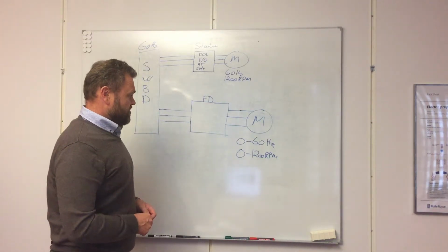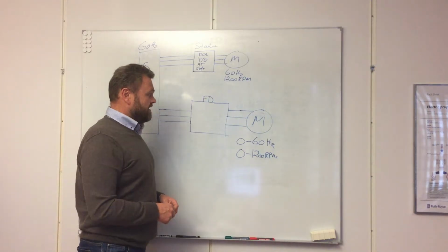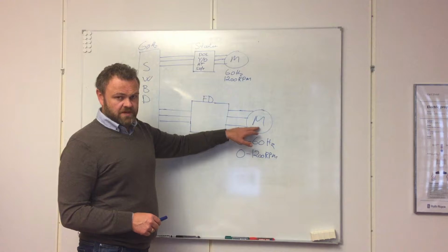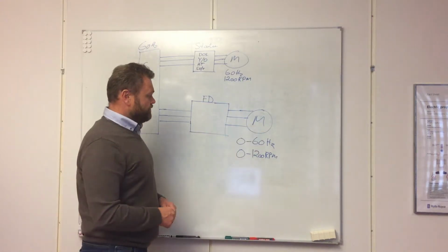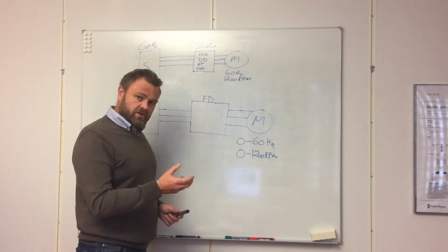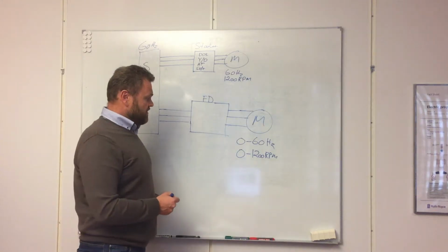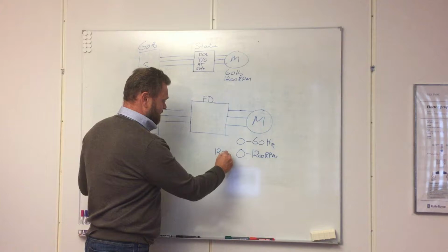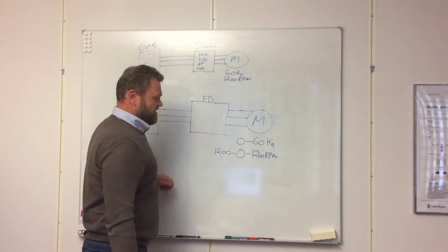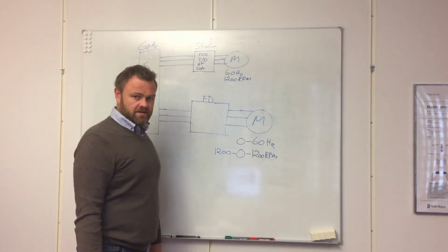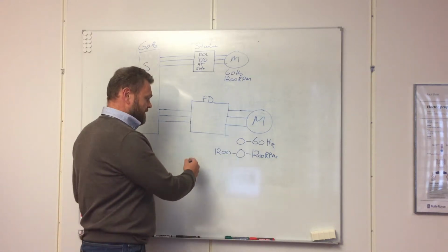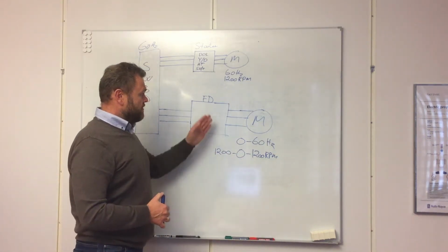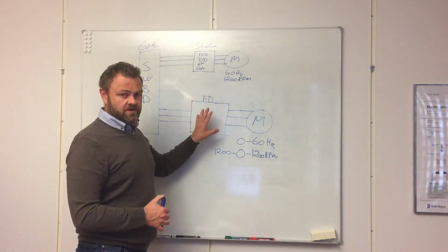Perhaps I should have mentioned earlier as well that you have the possibility with this one to turn the direction the opposite way. So you could say 1200 through 0 to 1200. So in both directions you have 1200 RPM controllable through the frequency drive.